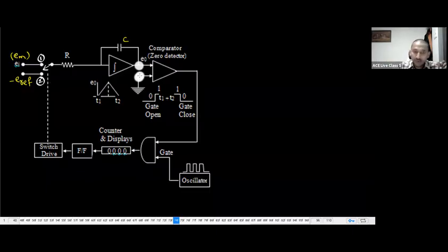Yes, 0 and 0 means this zero detector gives zero output, or no output. It is a comparator. This will be compared with this 0, but both are the same. No output. If there is no output, at the gate one input is high, one input is low. Output is 0. So the count is not started, which means the instrument has not yet started.